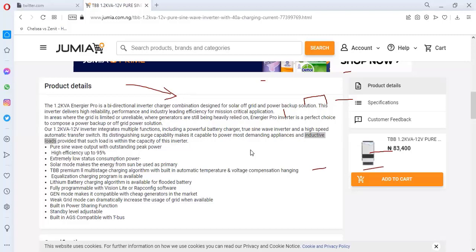But let's assume you haven't gotten any inverter you want to use. You can still use the utility agreed power factor, which is 0.8. So you can play safe with 0.8 power factor in your design. Any power factor lower than 0.8 is not so very good, but you can still have some inverter working lower than 0.8. So you just have to be very careful. Is that clear?